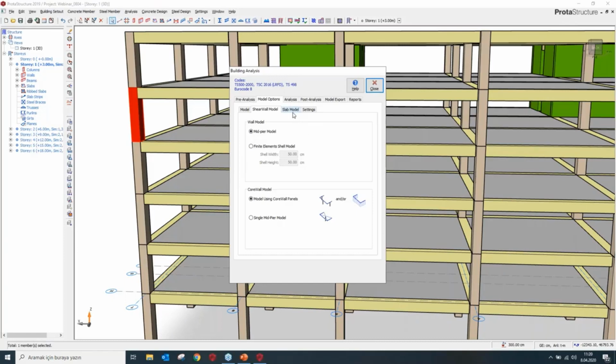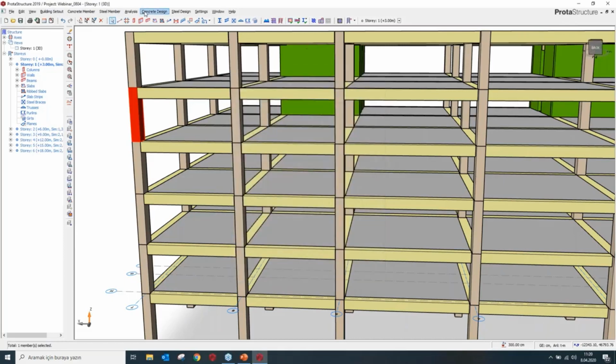Secondly, in order to decrease the load of analysis, you should not include slabs in the building model. However, you can use finite element load decomposition for more accurate slab load decompositions to beams. So you can use the load decomposition by finite element feature. So let's have a quick overview of the assessment user interface.